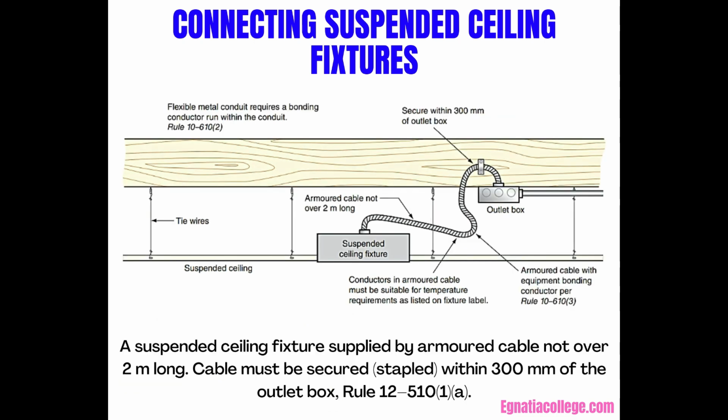The flexible connection can be up to 2 meters long and is usually made by installing either of the following items. Flexible metal conduit with conductors suitable for the temperature requirement as stated on the fixture label, usually 90 degrees Celsius, Rule 30-910-1.